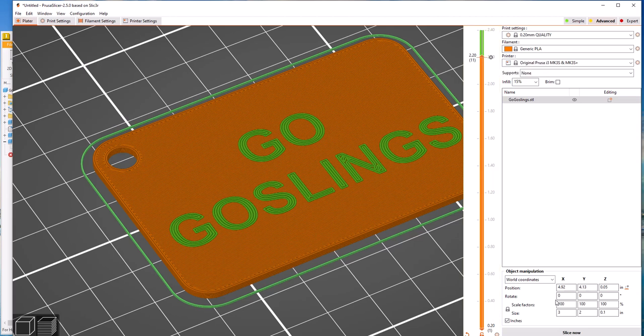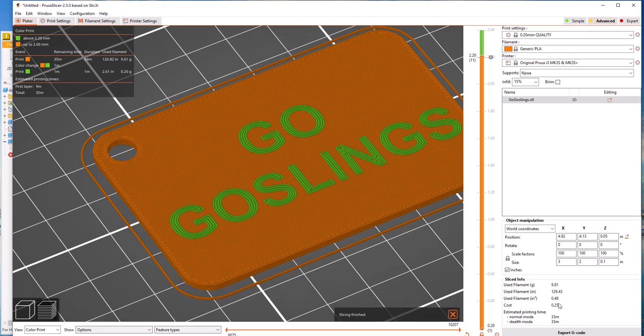So if we look at this particular print, slice, this is a 35-minute print. It's towards the end, so theoretically, about a half hour in, it's going to ask you to change filament. So make sure that you are there for that. We can actually look at these settings over here, and it says at the 34 minute mark, roughly, it's going to ask for the color change. So if you're not going to be in the room at that time, don't start your print or wait to run it at a different time. So that's definitely a neat feature that you can do color changes mid-print.